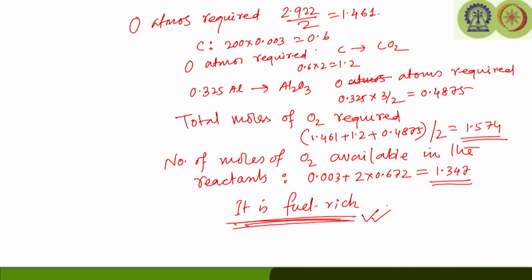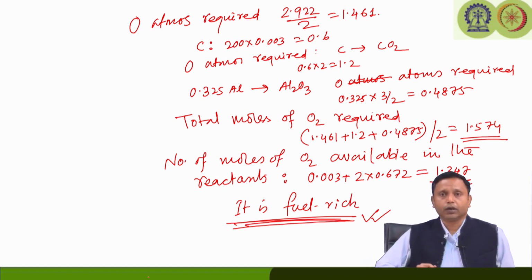One can actually do the solid loadings ratios just by calculating the amount of solid mass present in the propellant and divided by the total mass of the propellant. And similarly, if the solid ratio is given, one can actually find out the composition as well. So, these tutorial problems actually help to solve some of the assignment problems later on given to you.